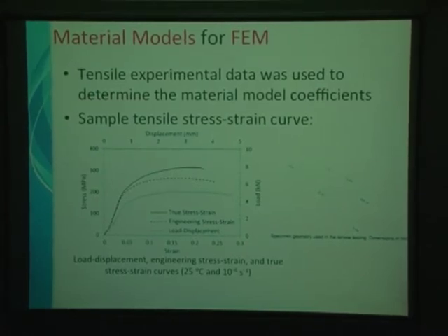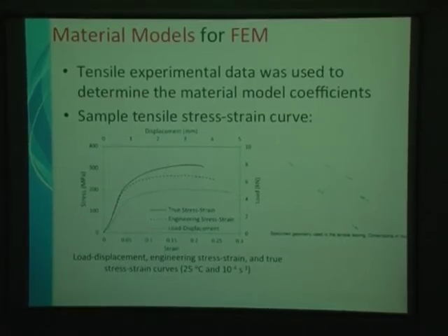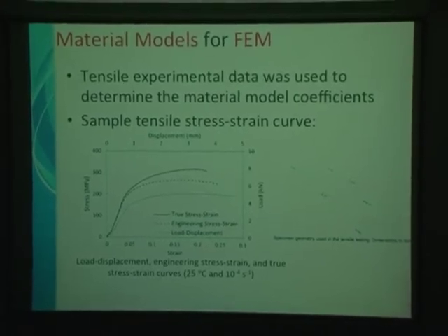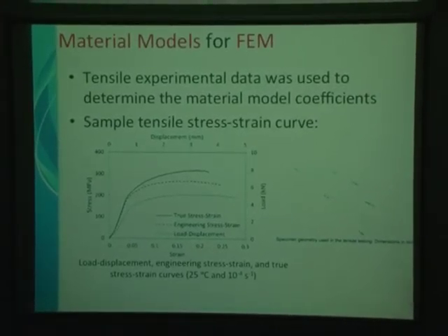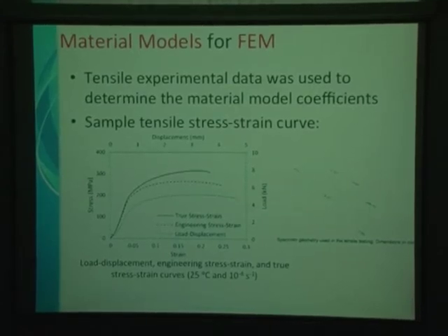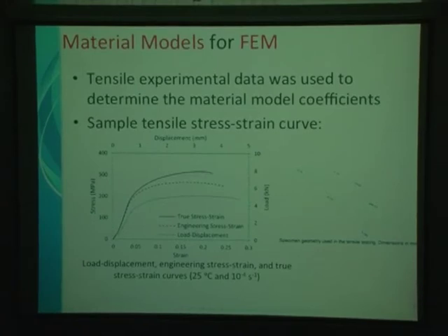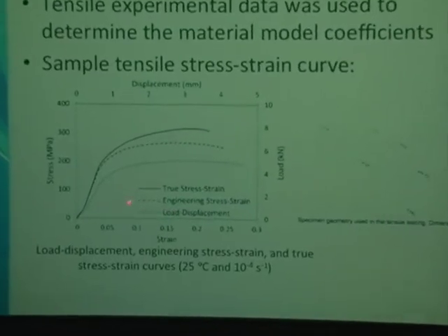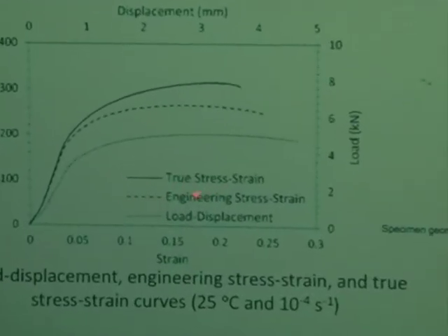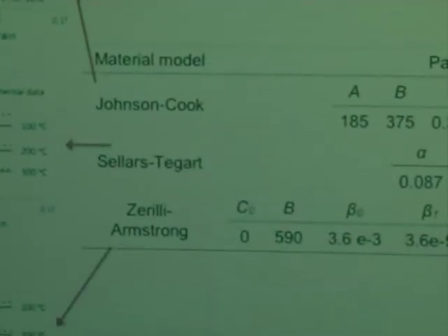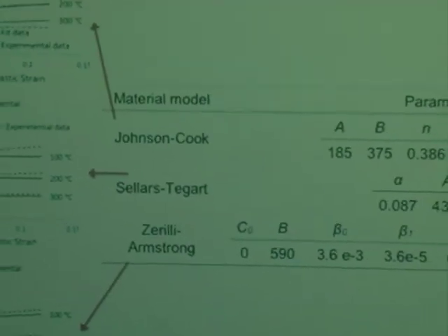Before we go into really high strain and high strain rate regimes, we'd like to see if those models actually allow us to predict something very simple, just like how a dog bone tensile specimen will be modeled in FEM with those models. Is it a good model or is it a bad model? So take a look at your true stress, true strain for the dog bone specimen, and you look at how these models will compare. All right, so again, those are reported models.